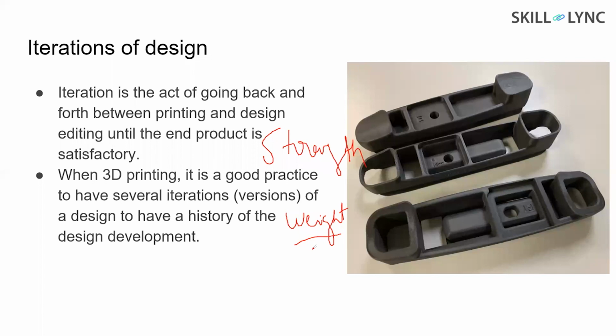So in this particular case, what you need to do is make sure that, in this example, what we did was, we had a complete material with completely solid parts. This is completely solid, this is completely solid, and all the rib thicknesses are much higher. We wanted to reduce it by compromising. We reduced it to a bare minimum to see if this particular part is performing properly. This part was not performing properly because it had very little thickness and low strength. So from this we got to know that at certain areas we need to improve the strength, and at certain areas we can remove material.